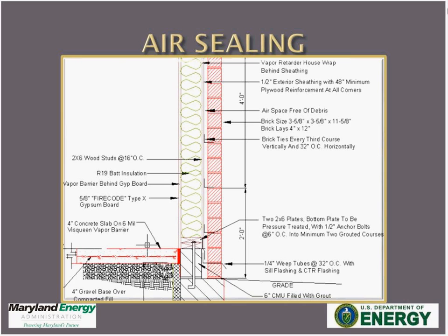Many of these requirements can be called out in the general notes within the documents as well as indicated in the sections. Here, near the top of the section, we see vapor retarding house wrap being used. If that was revised to include being taped and sealed per manufacturer's instructions, it would clearly indicate to the code official that this is intended as the air barrier. At the plate/foundation wall junction, this should be revised to indicate some type of sill seal to be used.